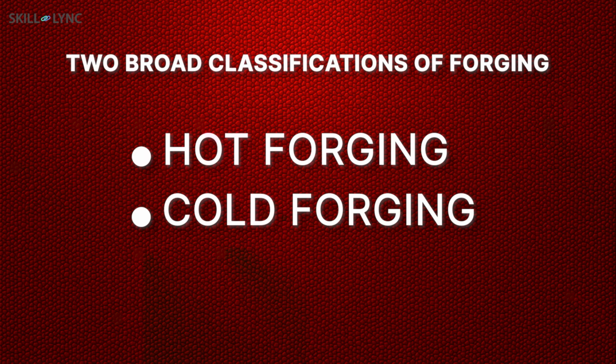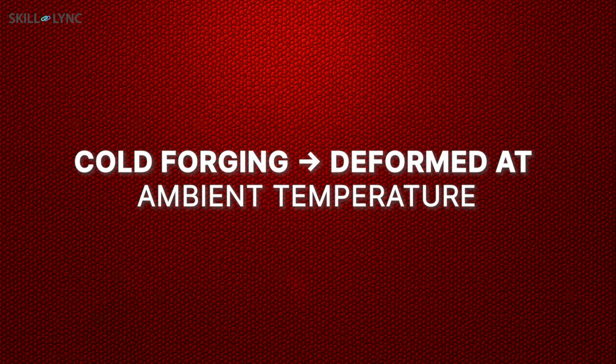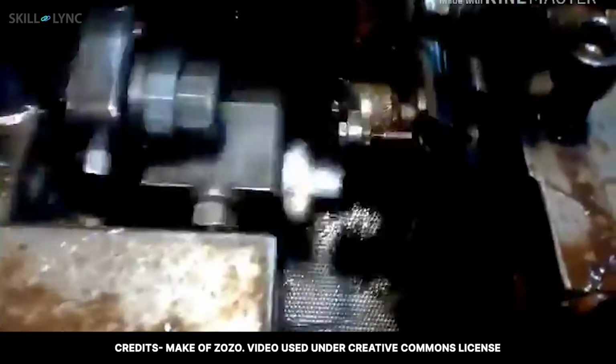Forging is broadly classified into hot forging process and cold forging process. Just like the name suggests, the hot forging process is when the metals are plastically deformed above their recrystallization temperature. In cold forging, the metals are shaped in the ambient temperature, and this is usually below their recrystallization temperature. Cold forging is most commonly used to make small metal items like screws and nails. It is also called a chipless forming process, as it often requires no machining to be done.